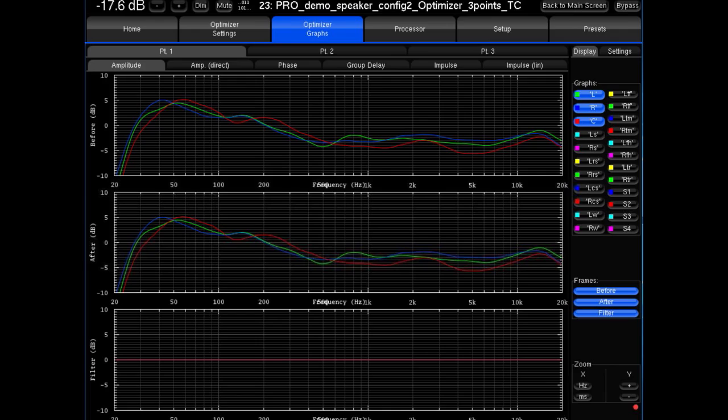Now, if we were to put a wider directivity speaker, like a normal speaker that had cone, mid-range, and dome tweeter, you wouldn't see nearly as much difference in level at 1K compared to like 100, for example. You would see a lot less. So any kind of automated system isn't going to know which speaker's there, and it's going to EQ the two very differently.